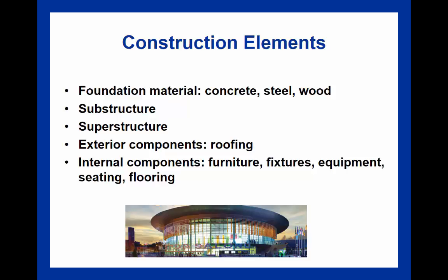Here also the facility builder needs to worry about preventing moisture from penetrating concrete and getting into the structure. So maybe using crushed gravel or stone would be helpful, and anything that's going to help the foundation transfer the building weight to the earth below. That's really important when you're talking about the substructure and the foundation working together.